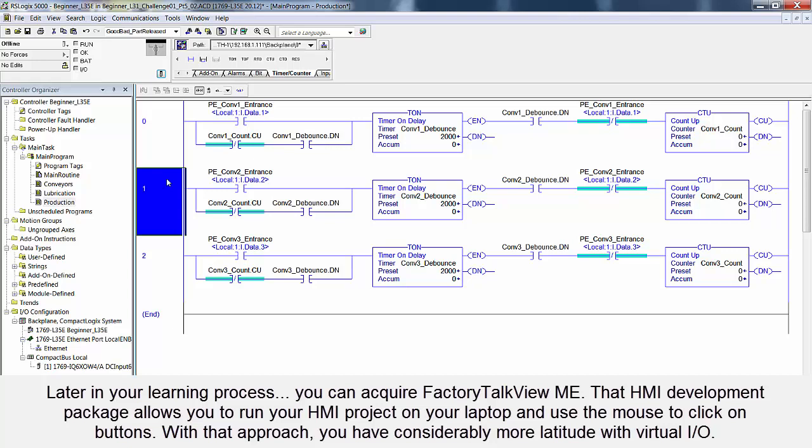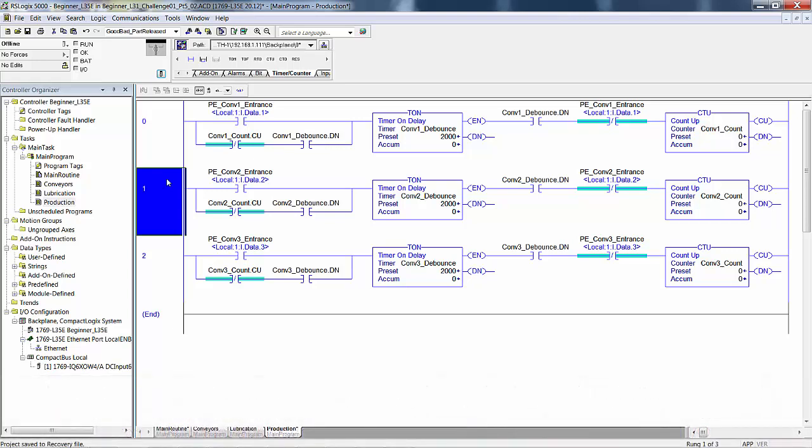Now this is one of those logical approaches that you have to try online in the run mode to make sure you have understood the behavior of the count up bit, because we did not do the count up bit when we were doing counters. The 2-second debounce is there to eliminate double counting when an object or part bobbles at the PE, or like I said, your best friend walks by and passes his hand in front of the photo eye to be funny.